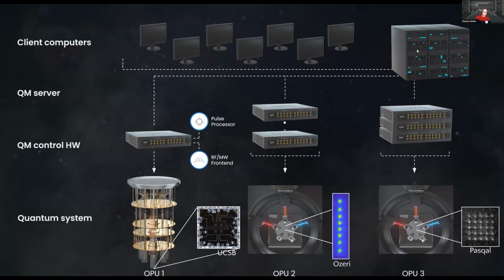You can also have one box because it's a multi-core processor. You can split the box into 2 or more parts and say, okay, channels 1, 2, 3, 4, and input channel 1 and digital outputs 1 and 2, they are reserved for experiment number 1, and output ports 5, 6, 7, 8 are reserved for a different experiment. And then 2 different students or 2 different operators can run completely parallel operations on the same box and not even know that the other one exists.